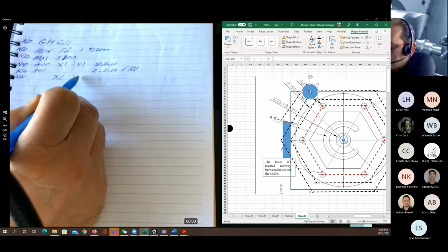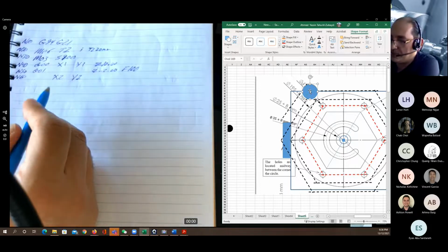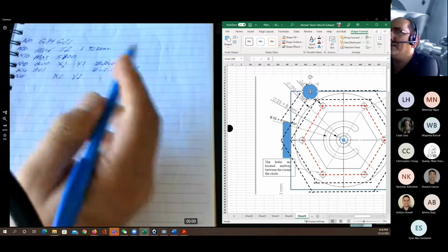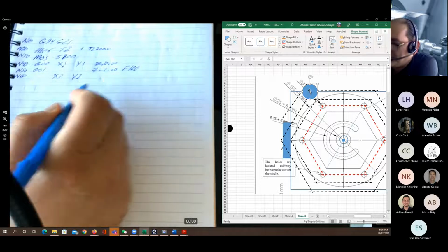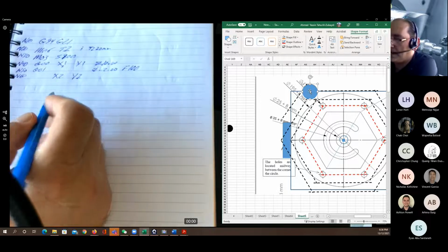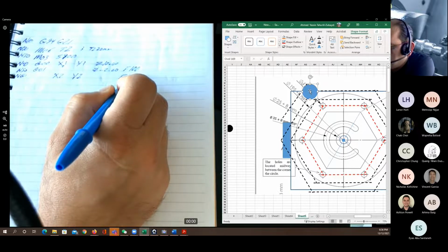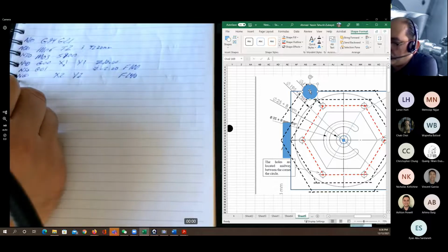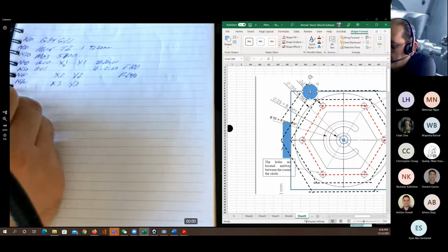Of course, when you write down the code, you should put numbers instead of the variables. Maybe I should do it smaller, right? This will be the correct way. Anyway, I'll do this one later. The feed rate will remain the same. No, actually, I can make it faster because this will be a rough cutting. So it's going to be 240, for example. And of course, the operation will continue with X3, Y3, X4.